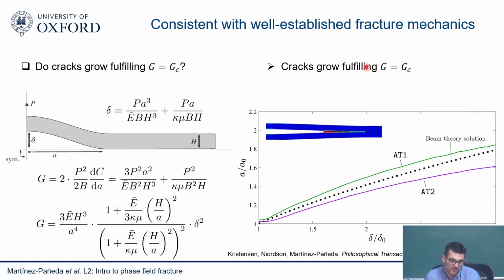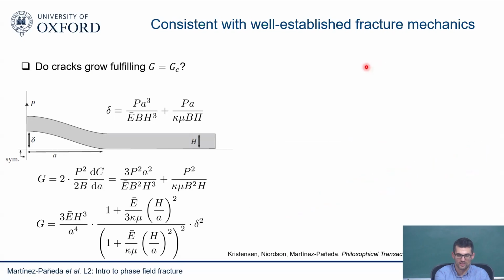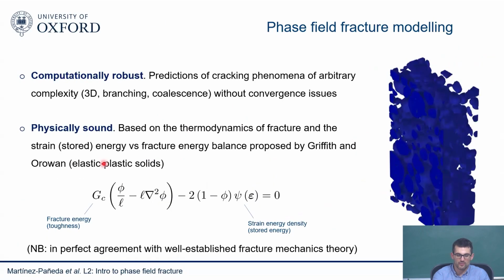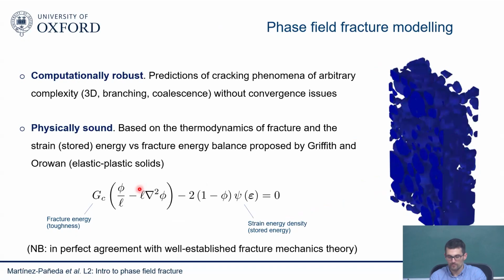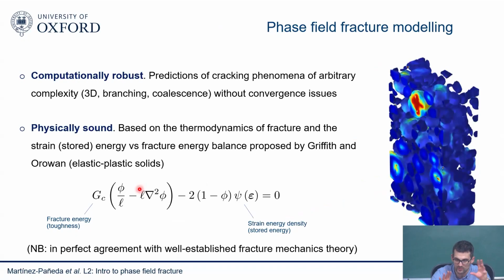So I think the main difference that I find with phase field and other, I would say, non-local continuum damage type of models like those, is that first, you'll see later the value of the length scale. Basically, if we look at the equation, it's non-local, but other approaches are also non-local. But it's also based on fracture mechanics theory. So everything doesn't rely on some critical quantities that we don't understand, critical damage parameters that we don't know. Everything is based on the length scale that I'll discuss later, and the toughness. And for material toughness, we have extensive databases. So that's on the physics side of things.